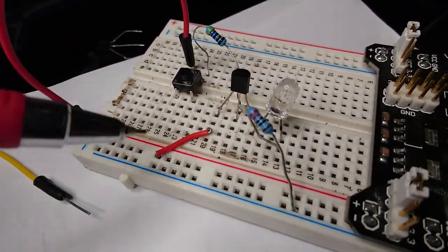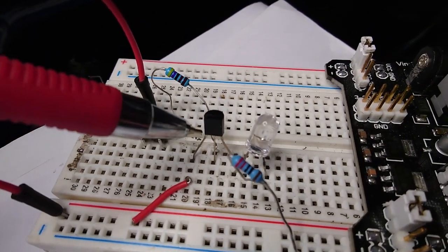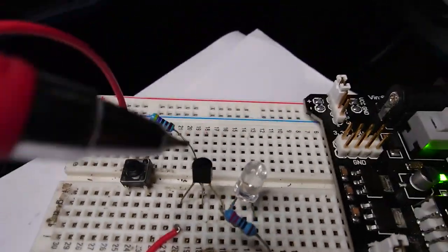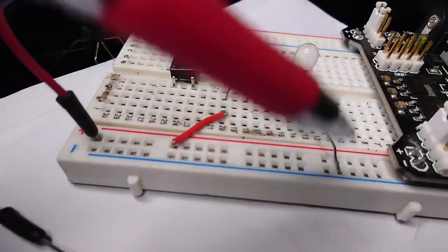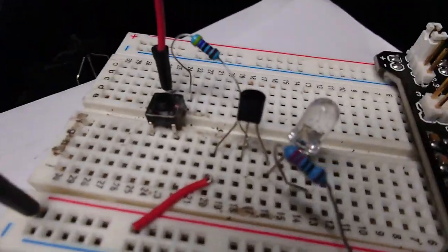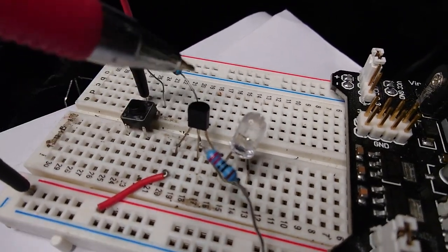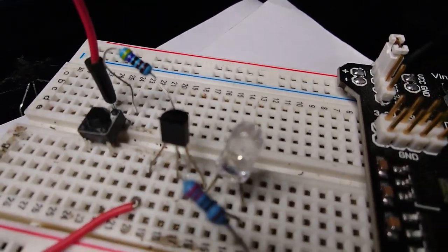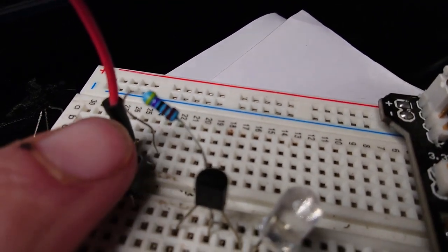Okay, anyway, so these little black bits here are called transistors. And what happens with the transistor is the power, or the current, can flow through here. And if the transistor is off, then nothing can flow through the rest of the circuit and back to the negative. So we've broken the circuit. The way that we turn on the transistor is to provide a small amount of current, usually via quite a big resistor, in order to stop things being overpowered.